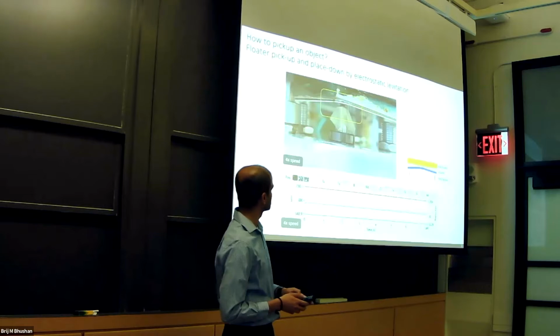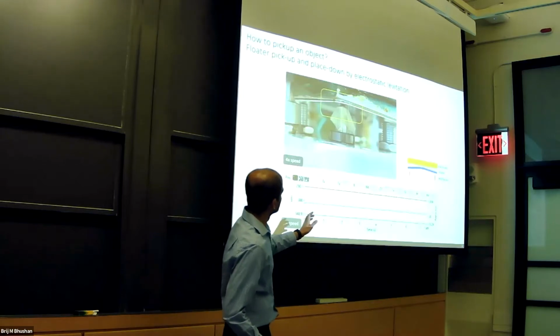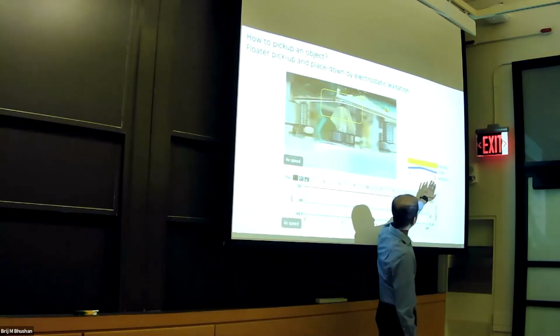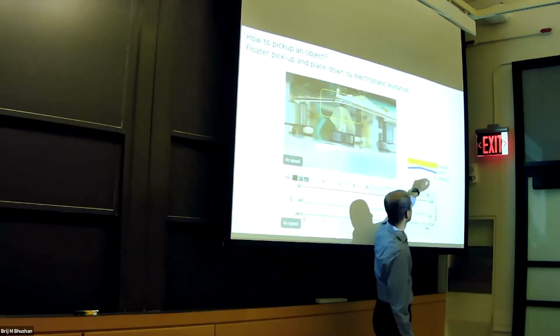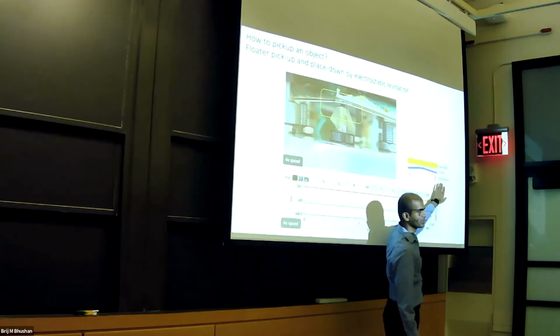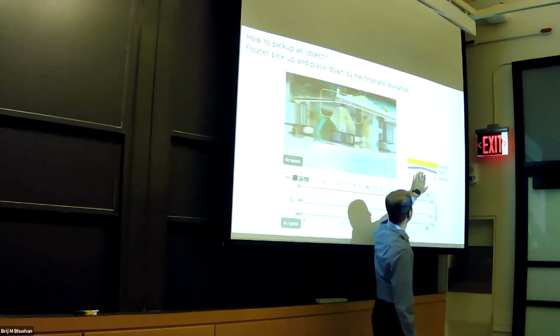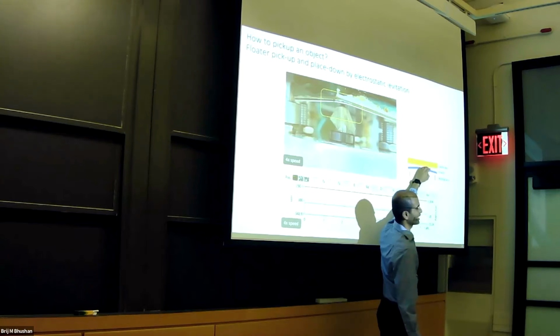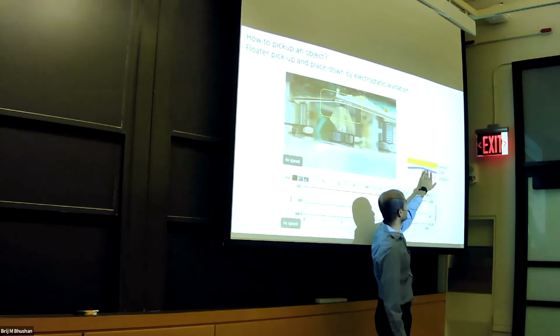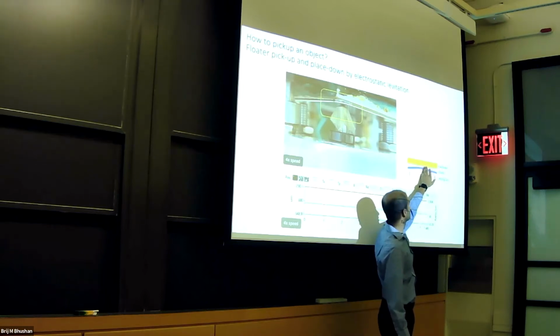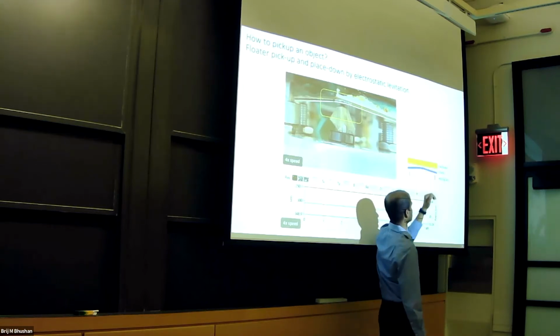More specifically, we use electrostatic levitation to transfer the object from a pickup stage, so if it is on the resting pins over here, to the electrodes on the other stage. We transfer the object by electrostatic levitation such that it's levitated and stable in 6 degrees of freedom. We also create a bow such that it contacts at the center first and then clamps upward.